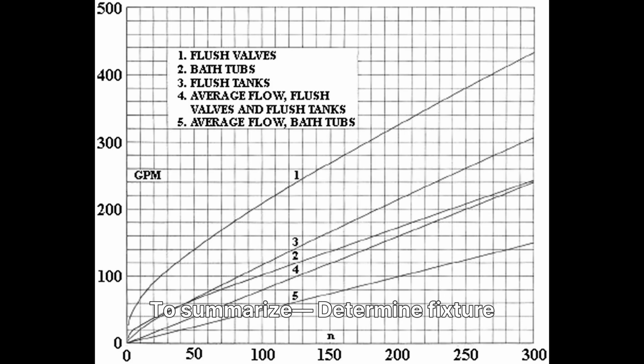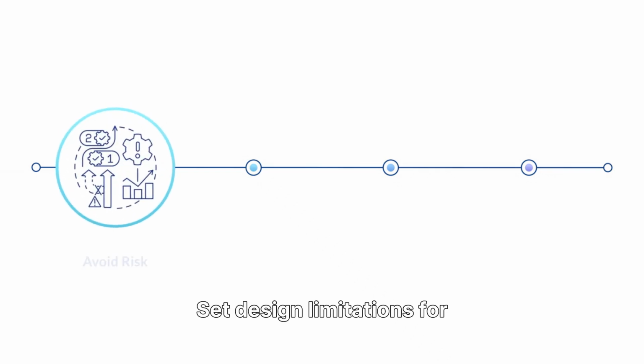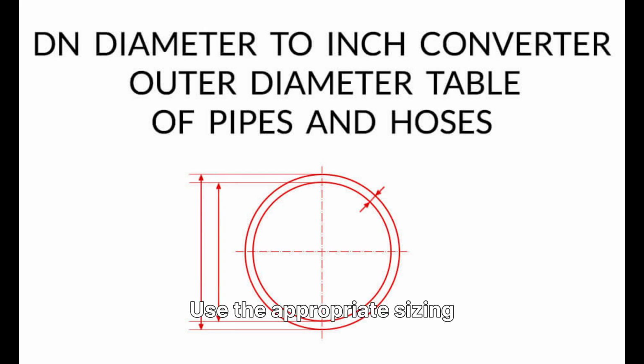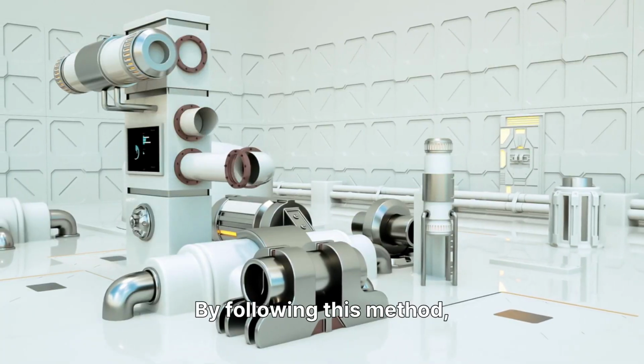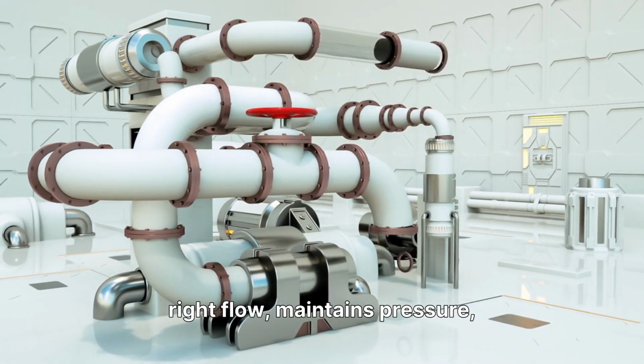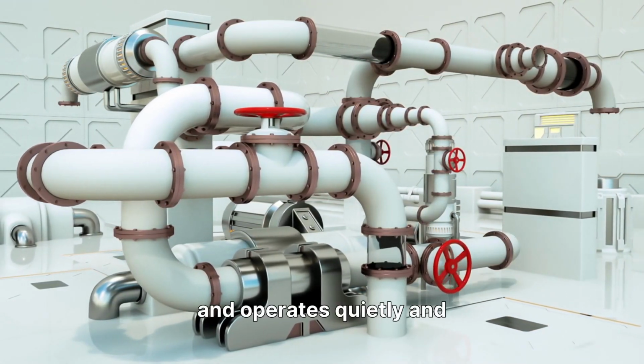To summarize, determine fixture unit counts and convert them to GPM using Hunter's curves. Set design limitations for friction loss and velocity. Use the appropriate sizing charts to select the correct pipe diameter. By following this method, you'll ensure your domestic water system delivers the right flow, maintains pressure, and operates quietly and efficiently.